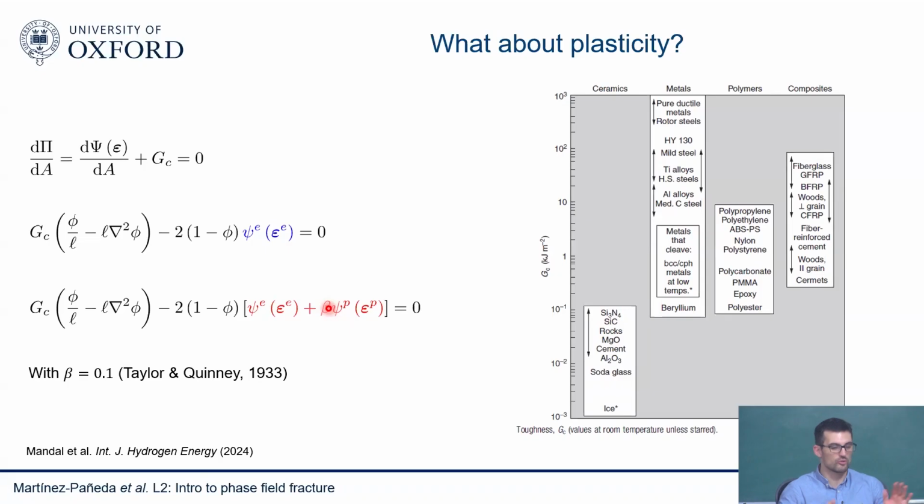So at some point, you may wonder, when does the Griffith energy balance break down? I mean, thermodynamics might always apply, right? You could have a situation where if you have a lot of plasticity, you're also heating that area. So then if you want to draw a full rigorous thermodynamics picture, you must build that heat balance into the picture. We don't look into that because we're not looking into those kinds of problems, but I agree if you wanted to, you could in principle, because you have these thermomechanical calculations where you're calculating where the heat goes and so on. But in principle, the only thing we need to know here is what percentage of our plastic work is being stored in the material and therefore it's available. And we take 10%, and we believe that this is rigorous with thermodynamics of fracture and so on. I think that's the idea.